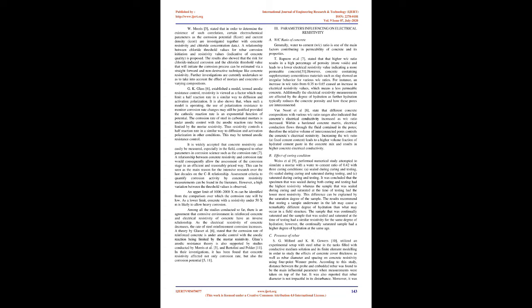Among all the studies conducted so far, there is an agreement that corrosion of steel in reinforced concrete and the electrical resistivity of concrete have an inverse relationship. As the electrical resistivity of concrete decreases, the rate of steel reinforcement corrosion increases. A theory by Glass et al. stated that the corrosion rate of reinforced concrete is under anodic control with the anodic reaction being limited by the mortar resistivity.